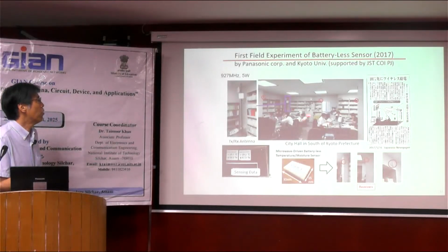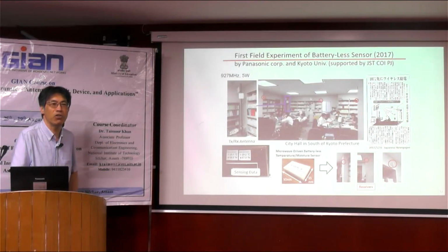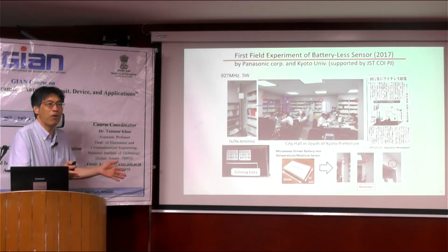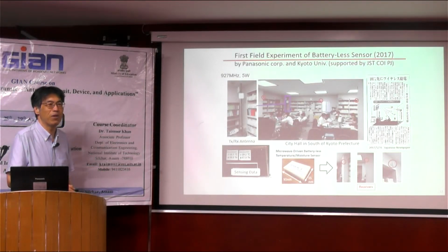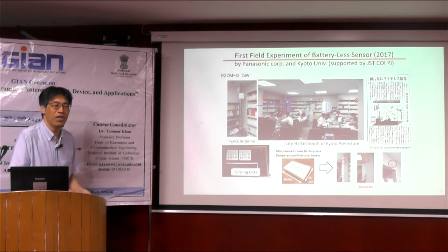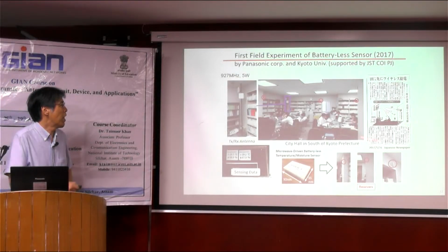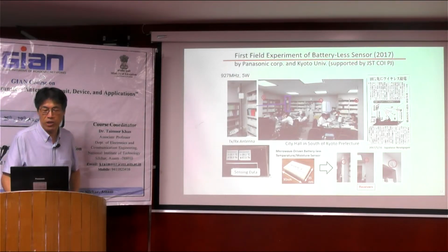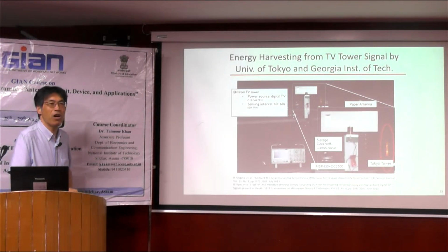So, for example, this is a collaborative experiment with Panasonic and Kyoto University. We put a transmitter there, like a Wi-Fi base station, and we provide the wireless power everywhere in the room. So this wide beam WPT system is very close to Wi-Fi itself. It's a far field WPT system and a wide beam WPT system. And instead of a special transmitter, we can use, for example, a TV tower for the TV broadcasting radio wave.